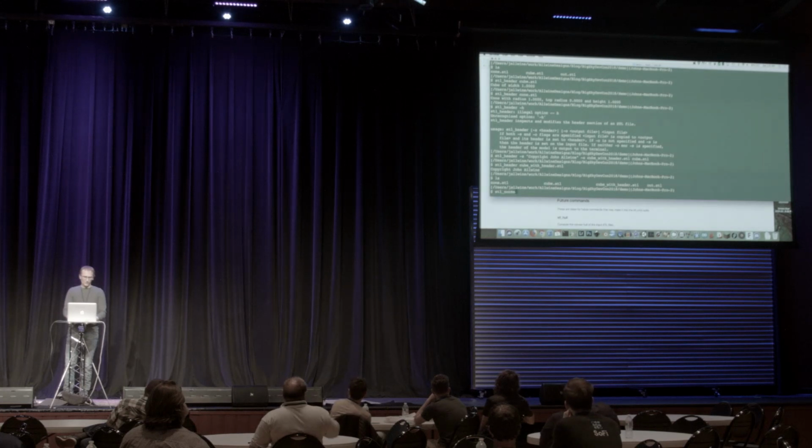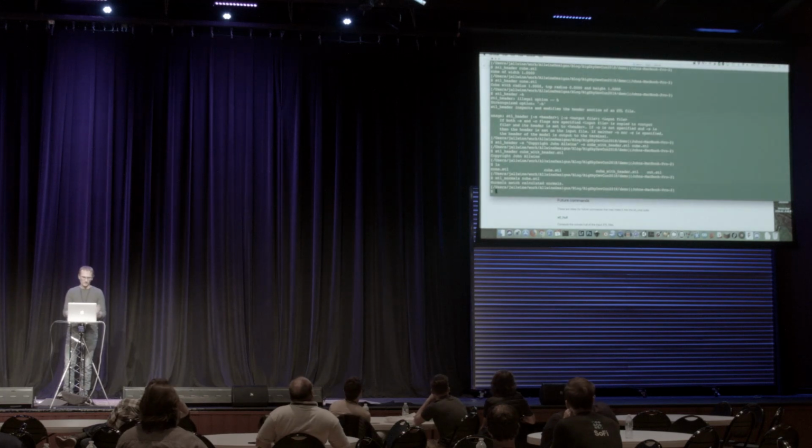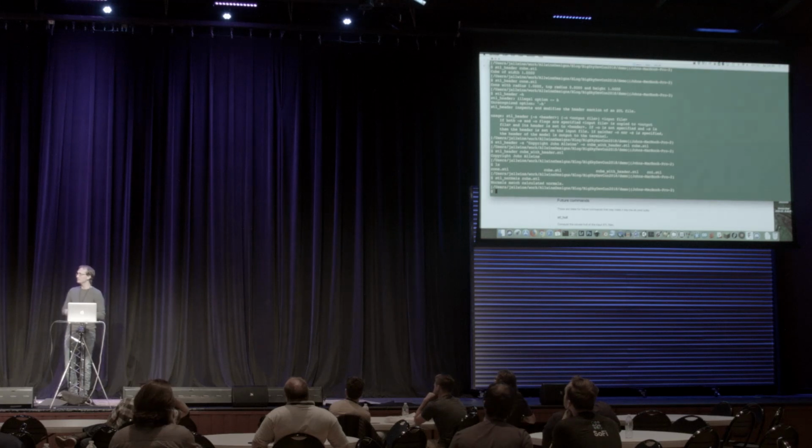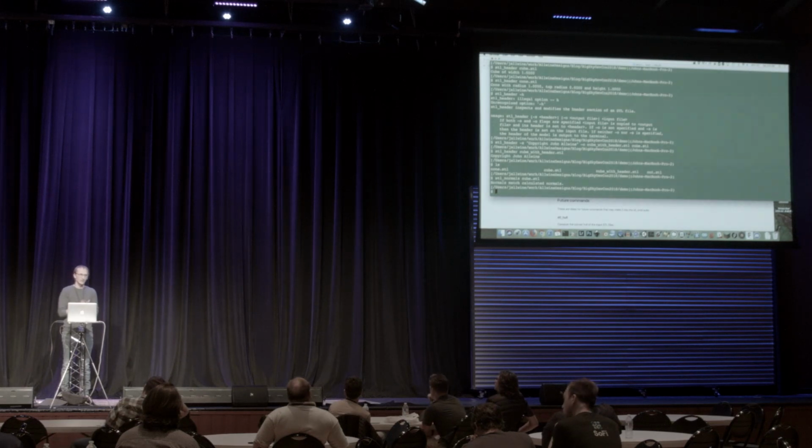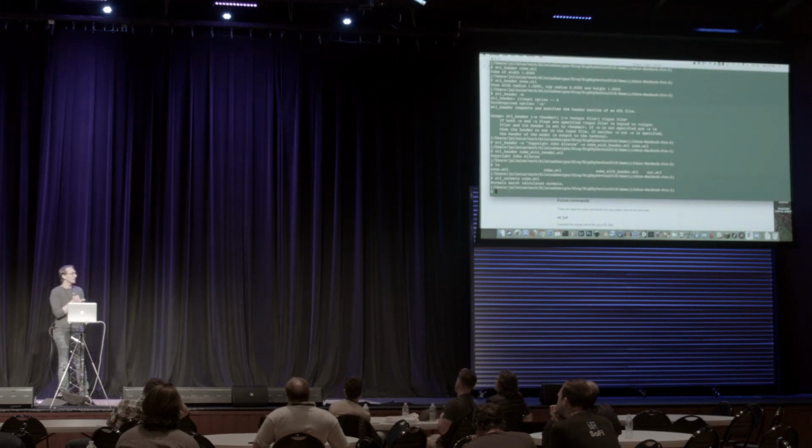Do STL normals. I just run that on cube. It says the normals match. So what does that mean? Each triangle has a stored normal. That's the direction that represents the outside of the model. Because you need to know what side is the outside or the inside of each triangle. And so that normal is what determines that.